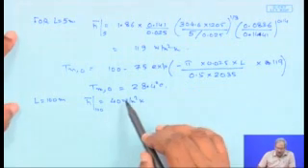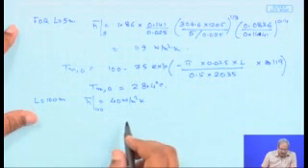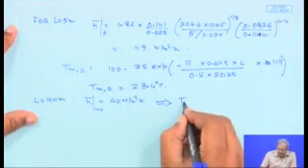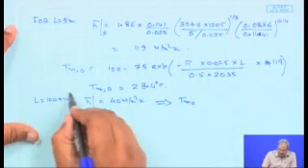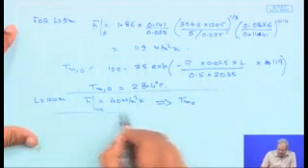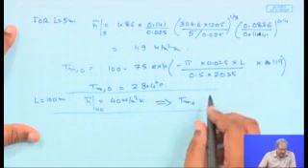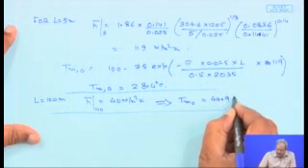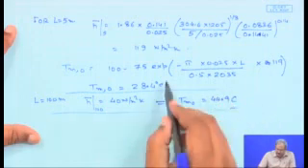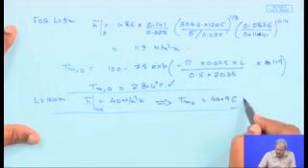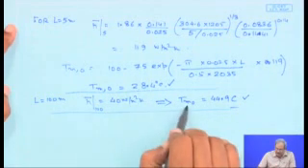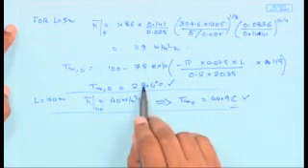So you would be able to see the variation of H with length, and when you apply this over here, the TMO for the case of 100 meters will turn out to be 44.9 degree centigrade.